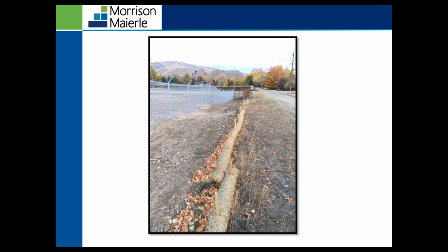This BMP right here is a straw wattle. It's also used as a sediment control. It's designed to intercept stormwater runoff, reduce stormwater flow velocities, capture sediment, and promote infiltration. It's most effective when installed at the site perimeter and at exposed areas, slopes, toe slopes, near water, wetlands, and pollution sources.